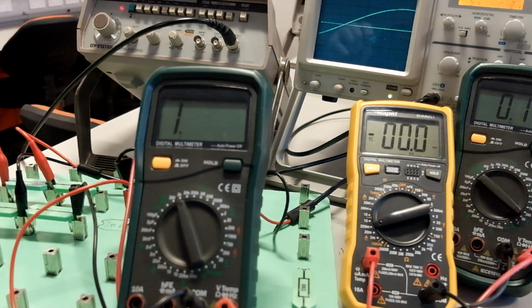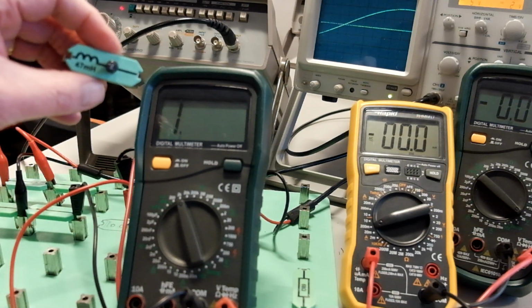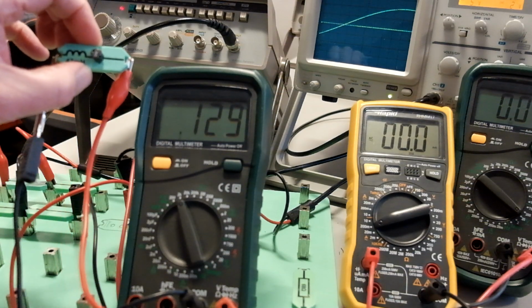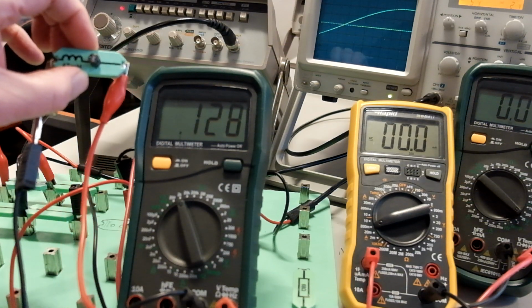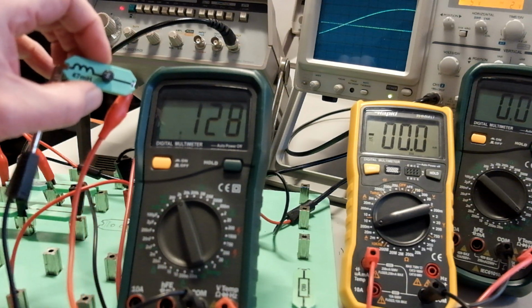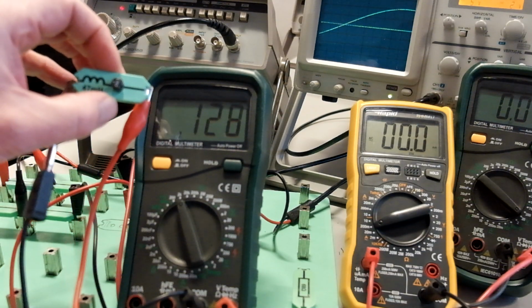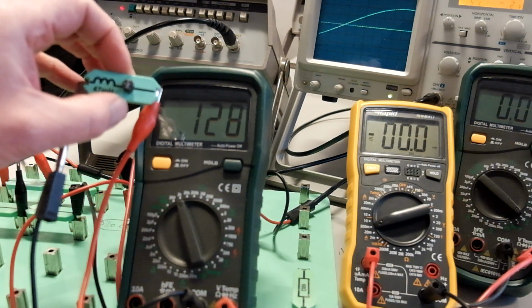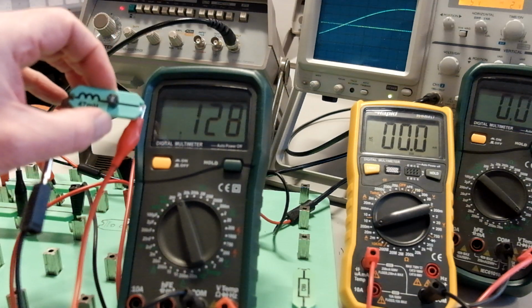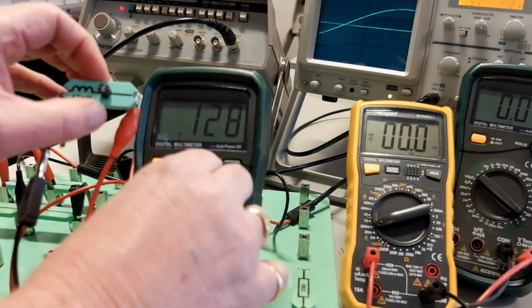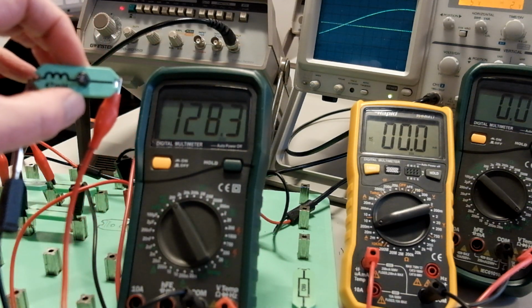However, what if we take the coil out? We can measure the resistance of this coil, and the resistance of the coil ideally should be 0. So using circuit theory, it assumes you've got 0 ohms through this coil. But on a physical circuit, you're never going to get 0 ohms. On this circuit, I'll put it down onto the 200 ohms range to get it more accurate.